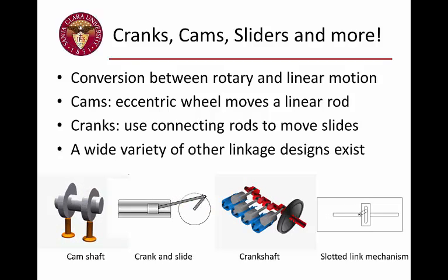You can see they interact, in this case, with two rods, push pins or pistons, and as the cam rotates with the shaft, it moves the piston vertically up and down. It certainly pushes it down. What isn't shown here, presumably, is maybe some sort of spring return that would push the pin back up. And you can use this to do all sorts of tasks. A very common one is when you push the piston down, it opens a valve, as an example, in an engine.